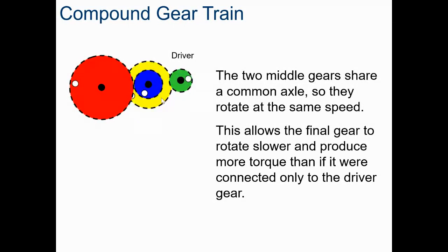And again, you can have multiple of these. You can have as many as you want. There are some practical limits about what can work or not work friction-wise, but a lot of them, like that Fisher Price little Power Wheels car we talked about, have probably 5 separate gear trains working together. I think it's 5, maybe more. But it's got multiple gear trains working together, so you can get really high ratios, and that's what you want.